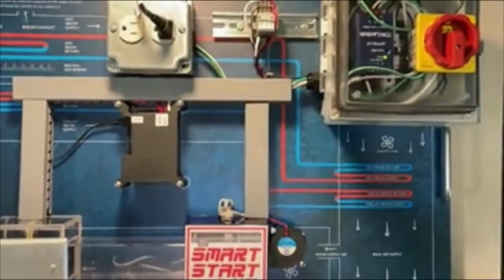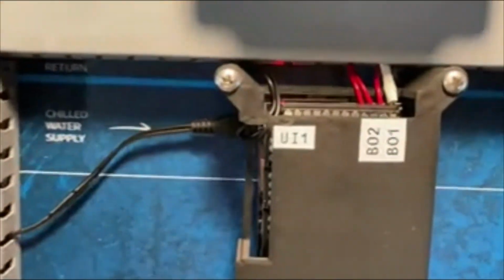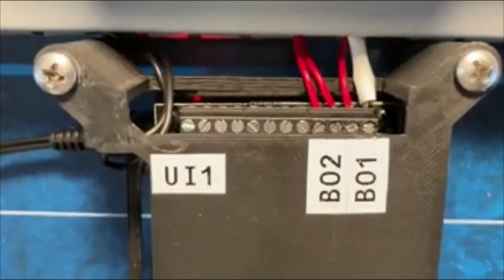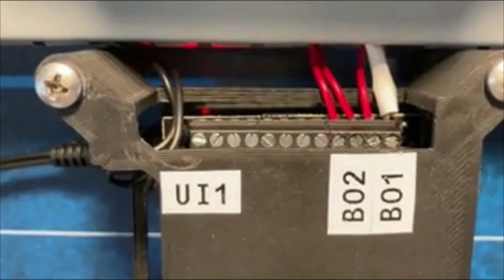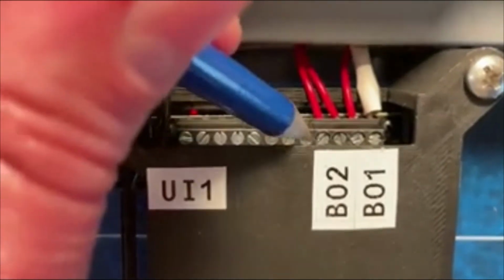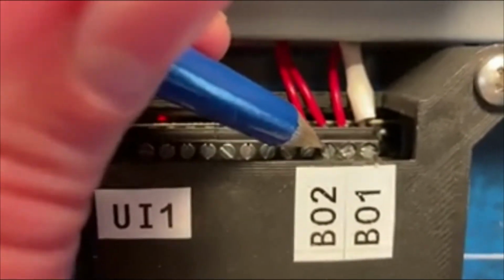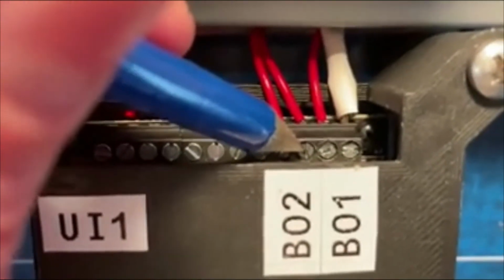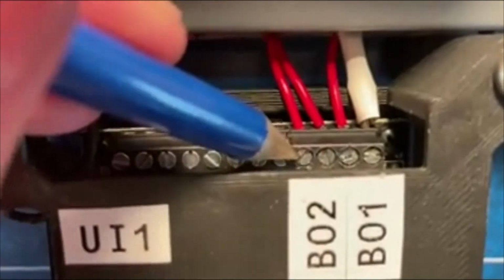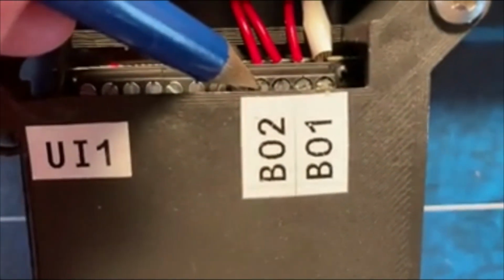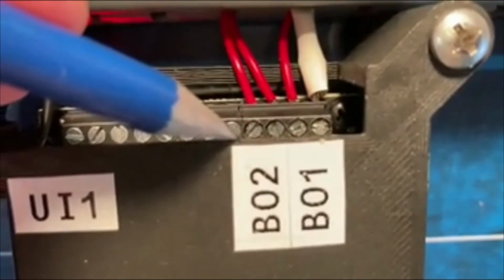As part of your lesson, you will explore how to measure the communication signals to and from the relay output on the controller. To do this, you will see if the circuit to the fan is either open or closed. And to open or close the circuit, the controller will open or close a relay that opens or closes the electrical connection between terminals 3 and 4, the binary output 2 on the controller. So binary output 2 controls the fan.